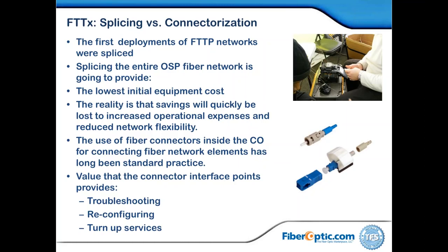And the answer could be both, but the reality is, even though connectorization, either pre-connectorized or field connectorization, adds a lot of loss, it's offset by the cost of a splicing technician versus a lower-level technician or installer doing the work.